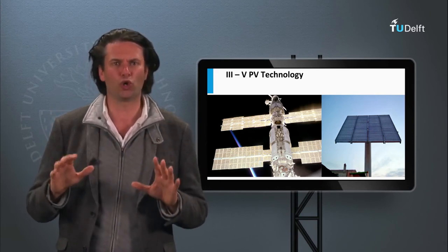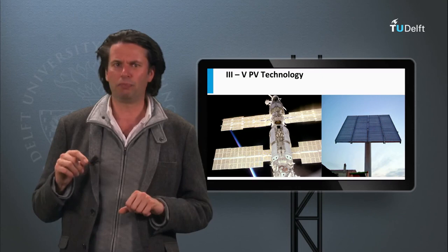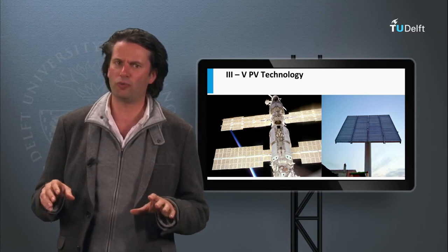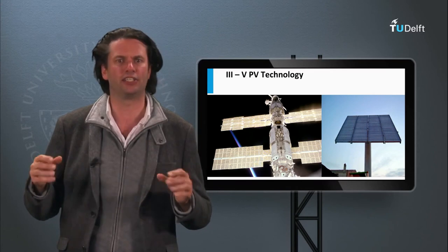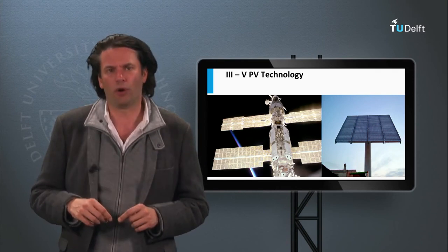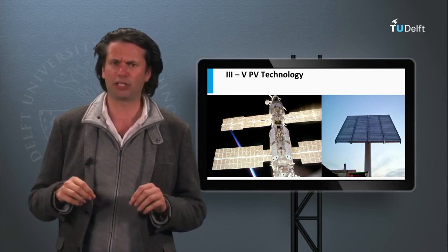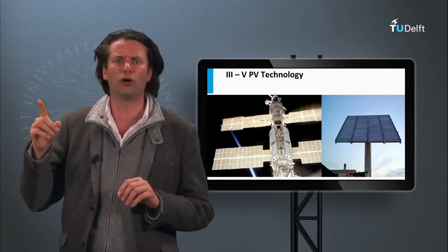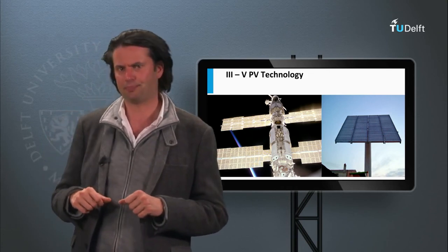Important is that the small solar cell devices have to be actively cooled. As will be discussed in weeks 7 and 8, the performance of PV devices goes down when they heat up. This loss in performance is a result of the increasing dark current of the diode component of a p-n junction. Furthermore, concentrator solar cells need sun tracking systems. These systems make sure that the optical concentrator system tracks the sun and guarantees the optimal light concentration on the small PV device during the entire day.